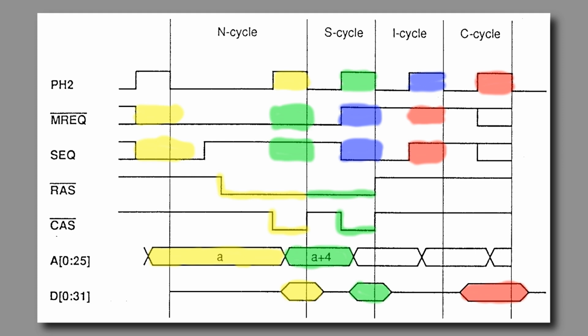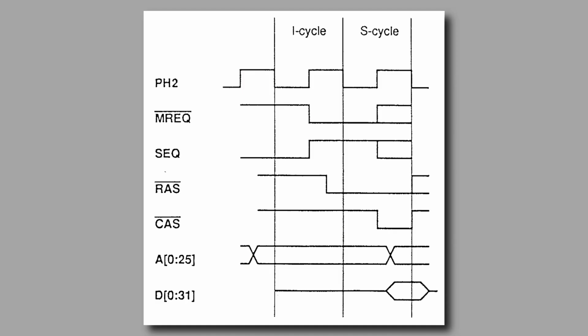But that also means that during these cycles when the bus isn't being used, the CPU does provide the address again really early through the pipelining, and that means that the next cycle can always be a sequential cycle because the CPU has provided the address so early that the RAM hardware has had plenty of time to spin up and get ready to provide that address during the internal or coprocessor cycle when the bus wasn't needed by the CPU.